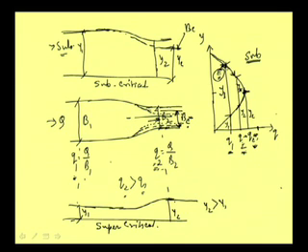So, what will happen? Water will start impounding on the upstream side, so that the energy level increases. In fact, this indirectly will allow the water to impound upstream, which will make the energy level higher at the upstream, and that higher energy level will push the water through this narrow portion.